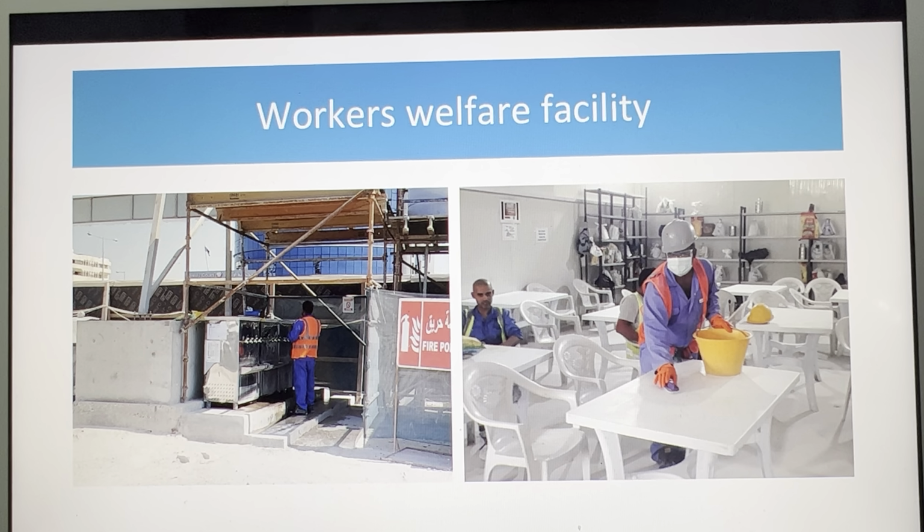The purpose of which is to ensure that whoever will visit or inspect, you don't need to go to your office to show that you had complied with the water laboratory requirements. All right, and the water filter behind this also complies with Qatar requirements, because I had taken this photograph myself and inspected the provision. There is a water filter here that complies with the Ministry of Labor circular. That water filter is ceramic and 3 candle.